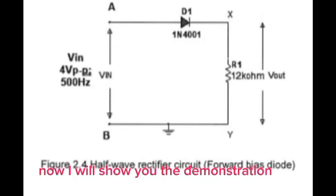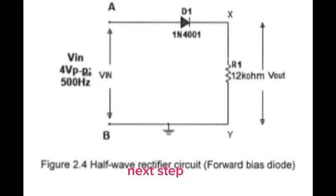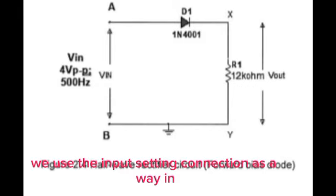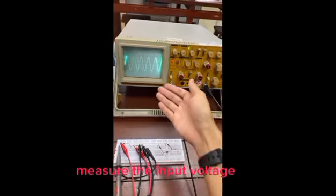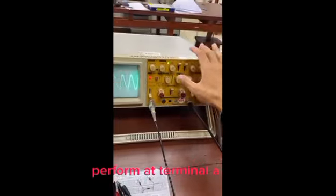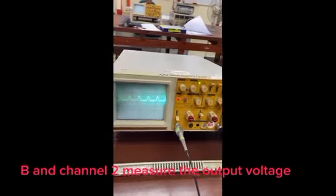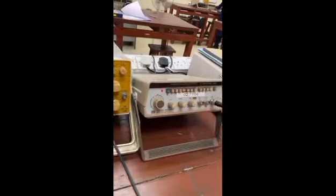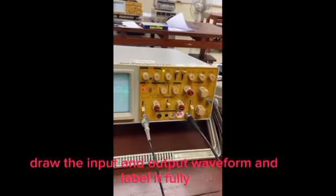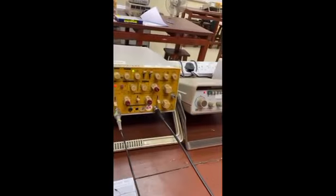Now I will show you the demonstration. First, we need to construct the circuit. Next step, we use the input setting connection as Vin for the circuit. Using the oscilloscope, channel 1 measures the input voltage waveform at terminals AB, and channel 2 measures the output voltage waveform Vout at terminals X and Y. Finally, draw the input and output waveform and label it fully.